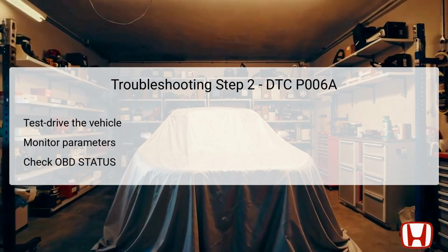In this step, the technician should take the vehicle for a test drive, maintaining speeds that correlate with the previously recorded onboard snapshot parameters. It is essential to monitor the engine speed, vehicle speed, MAP sensor voltage, and throttle position (TP) sensor during this phase.